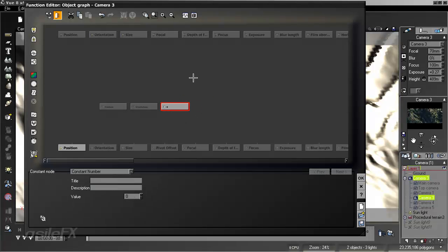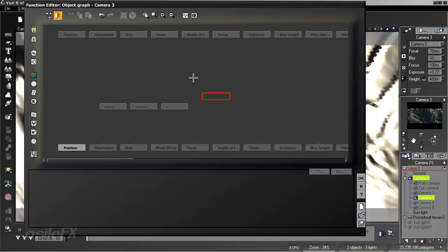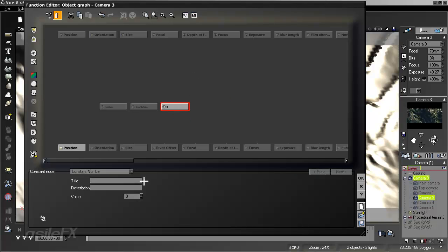This number output is actually set up for field of view and not based on focal length. So it does need to be manipulated. In other words, it needs to be divided by 2. So if we have 70 millimeters, we need 35 to be that number to connect to the focal to get it to return as 70 millimeters.